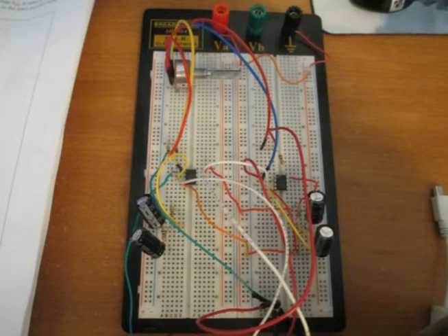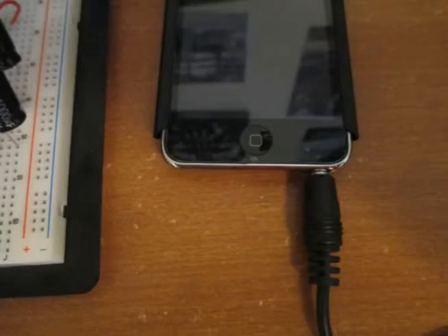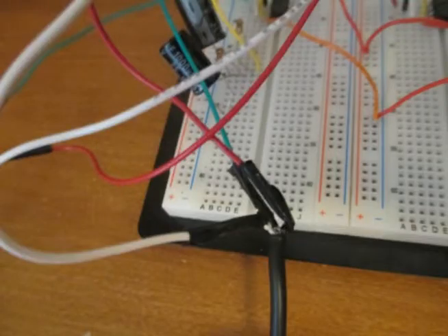This is our final circuit constructed on the breadboard. Two ICs were used, one for left audio and one for right. The capacitors shown are attached to the voltage divider in order to beef up the power supply for use with the op-amps. The input is connected to a cut-in-half cable, one end leading to the headphones, the other leading to the MP3. The aforementioned cable was cut and stripped to isolate its components, one wire leading to ground and the others leading to the op-amp. We had to solder the wires onto the existing ones and insulate it with electrical tape.